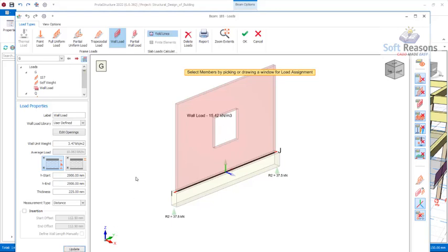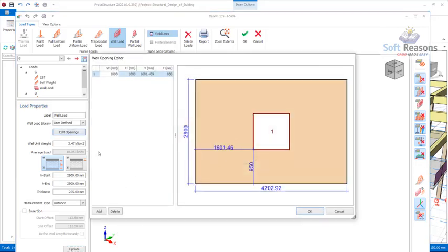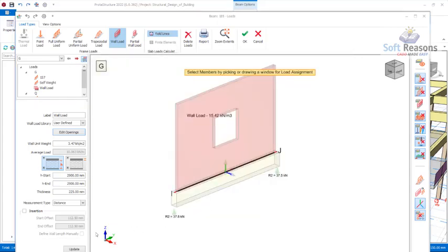Okay, so you can get back right there to the openings, and then you'll be able to delete, yes, to get rid of the window openings. Click on the OK option and then update right there to have your wall load applied successfully, which is 39.1 kilonewtons as reactions at both ends of these beams. Okay, so I believe this is understood. In areas where you wouldn't get it right, you can ask questions in the comment section.